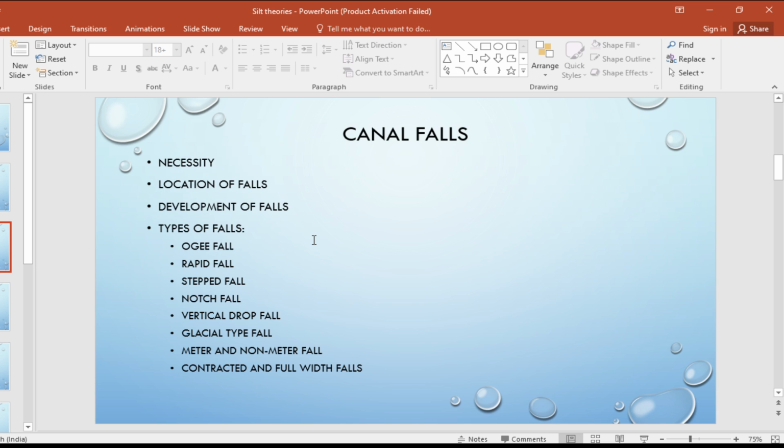ओके, तो जो भी कैनाल डायरेक्टली एरिया इरिगेट करेगा, वहां पे हम लोग कैनाल फॉल कहाँ प्रोवाइड कर सकते हैं, एट द लोकेशन वेयर फुल सप्लाई लेवल आउटस्ट्रिप्स द ग्राउंड लेवल। Okay, full supply level outstrips the ground level and before the bed of canal comes into filling.